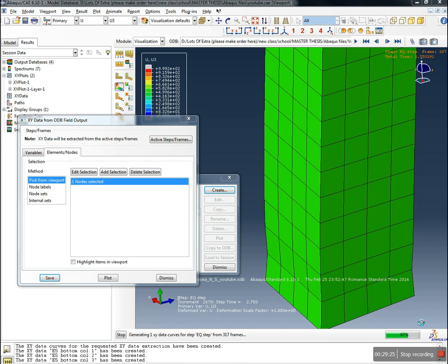And also to avoid the shear failure, obviously in our model we don't have any stirrups, but you can do it. You can just try to do the same model and just put stirrups, and then compare the response of the structure with stirrups and without stirrups. And what you're supposed to see there is that the strains are much lower when you use stirrups.